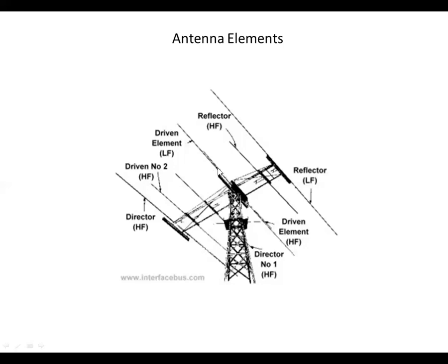Now this isn't driven, but when the electromagnetic field contacts this free space element, it'll induce a current in the element, just like a receiving antenna would. And because of that current, and the power level of the low frequency signal and the proximity to the driven element, it'll have enough current that it'll re-radiate that signal.